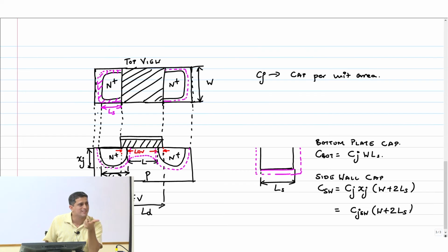Channel length is under the channel. It only depends on the width. So again we are going to do the same trick. We are going to split this as technology constant multiplied with some design parameter. Design parameter here is only W. L is not available here, even for analog guys, right?